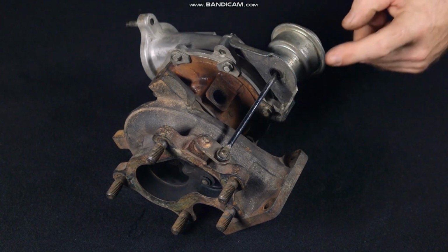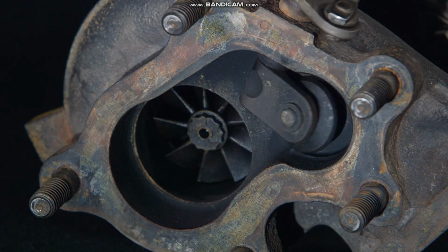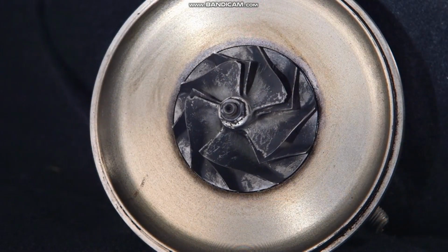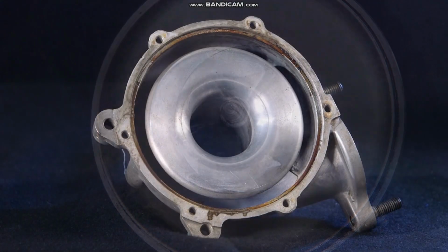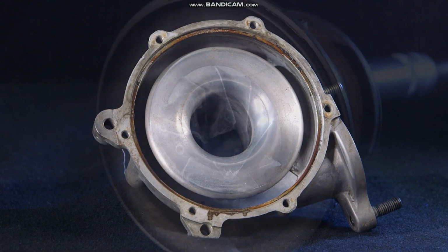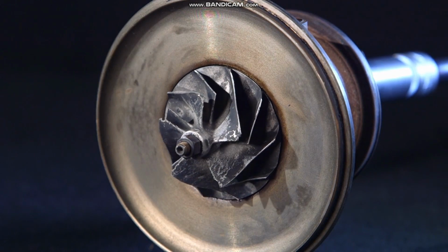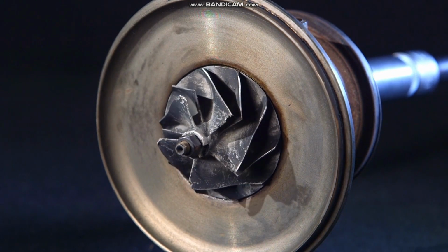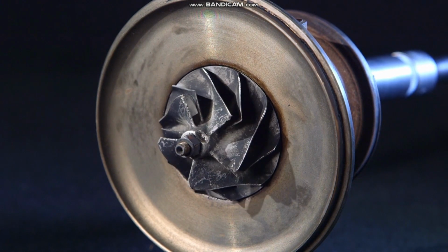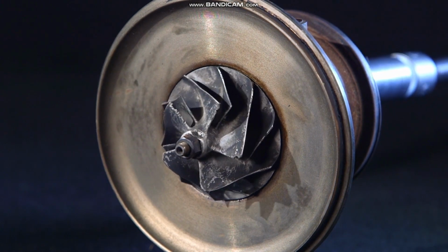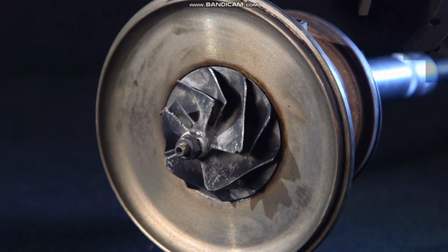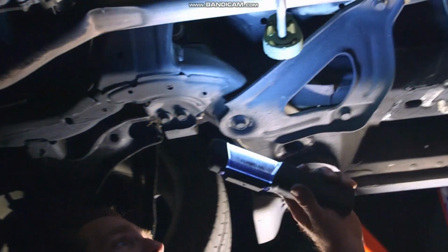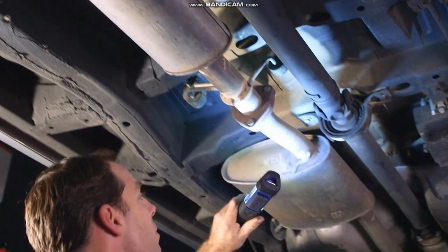On the turbocharger, check for seized or binding linkages, damaged or leaking vacuum and pressure hoses. Inspect the compressor wheel and housing for any damage. Pay close attention to the turbine shaft. If this is hard to rotate, boost pressure will be affected. If a shaft seizure or fault is found here, it will be necessary to check the engine oil pressure, supply and return. Inspect the exhaust system for any blockages downstream or leaks upstream from the turbine.